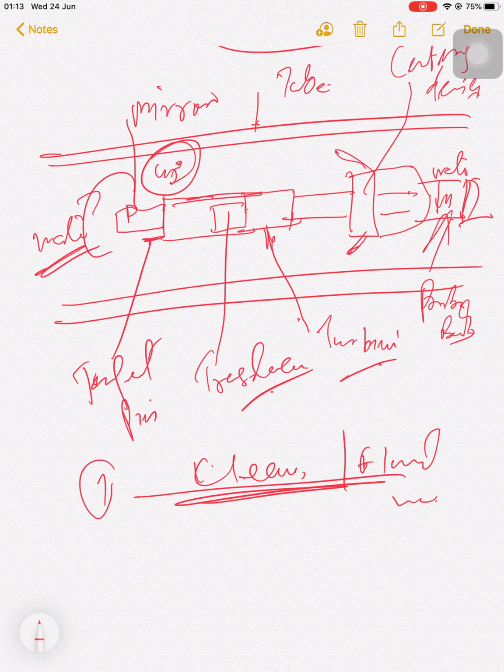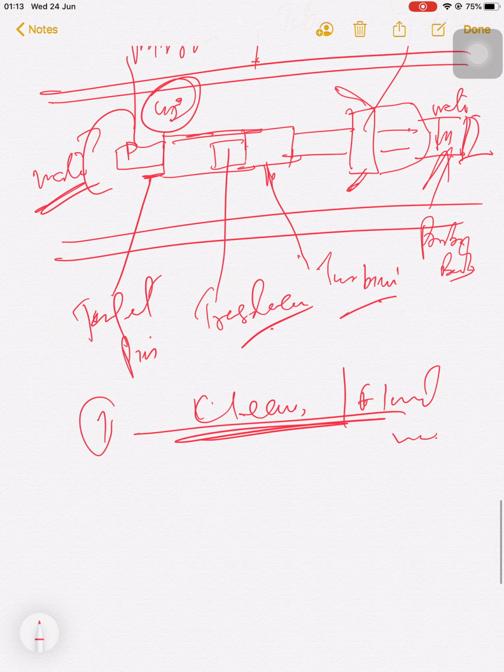The beam falls on the tube surface at a right angle. The beam is partly reflected from the inner surface and partly transmitted and reflected from the outer diameter surface. The time difference between the two signals is used to measure the wall thickness.